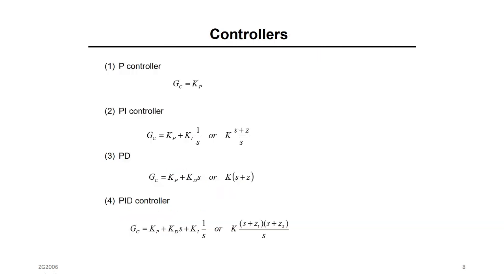All right. Now, what types of controllers do you see anywhere? There are always 4 types of controllers. Okay. P, most simple and the most popular, the proportional controller, gain. It's a gain. It's usually a positive number, 0, 1, 2, 3, 4, 5. Okay. PI, also popular. It's a proportional plus integrator. What do I mean by integrator? 1 over S. 1 over S is in fact the Laplace transform of an integral. Okay, that's why we call it integrator.